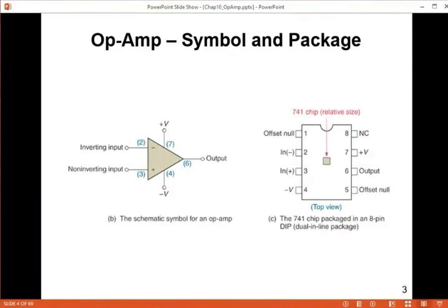As long as you do not apply a biasing voltage higher than the safe supply voltage, the op-amp will work normally in good condition. If you apply slightly below, your op-amp can last long. But you cannot apply the VCC too low. It has to be in the working range. So this is the symbol.